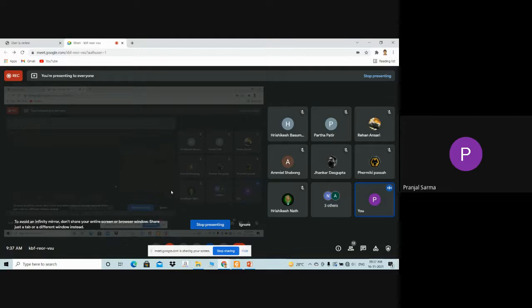The requirement is that there has to be a minimum of two gears, and definitely they should be properly matched. So they should be mating gears, two mating gears. For proper matching of gears, later on we'll discuss that the module has to be the same, and the teeth profile also has certain applications. But it has to be two mating gears. Only then, if one of the gears is rotating, our intended purpose, the rotation from one shaft to another shaft through proper engagement of the gears, will happen. Up to this much, I hope it's clear.